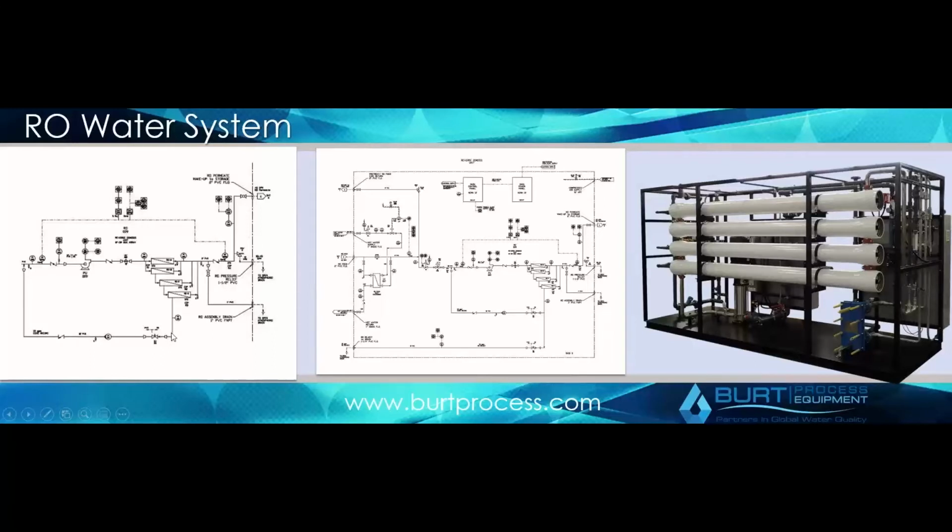And even a portion of the end reject is put back in. You actually need to have, quote unquote, dirty water essentially coming into your RO system to really allow it to operate properly. This is just a more elaborate version, where you see you have a heat exchanger for cooling. And again, here's the complete P&ID of an overall RO system.